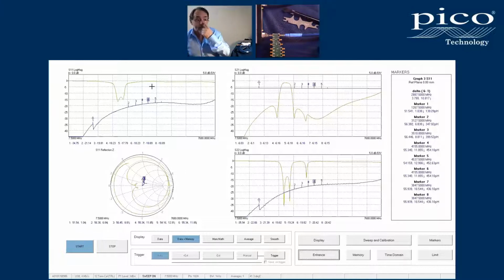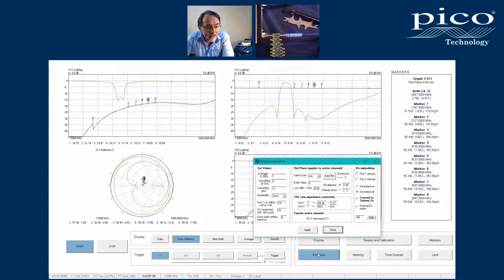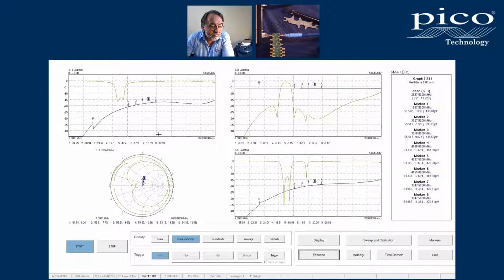So this should be very good 50 ohm match. Oh, here we go, look. We can see that measurement of S11 and S22 both got a small discontinuity in them. Let's reapply. You can see the discontinuities have changed, but I haven't been able to eliminate them with this type of correction altogether. So yes, we do have a discontinuity in our match measurements, but we are down below -35 dB, or down in that region with the discontinuity. So it's not going to upset us a great deal.